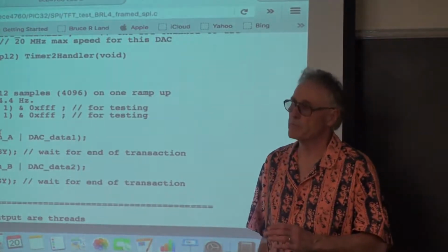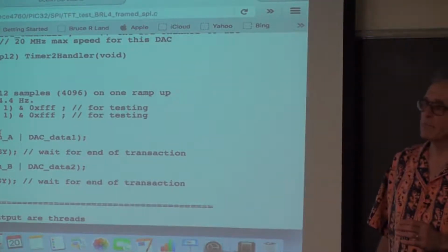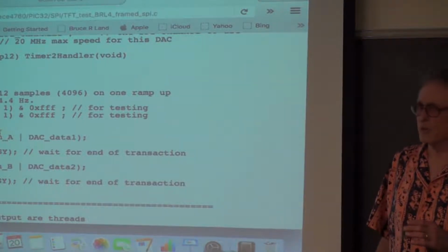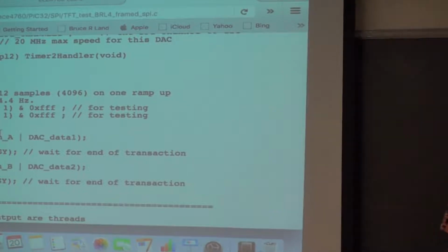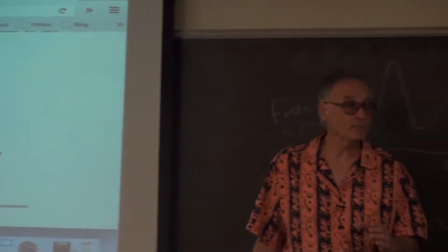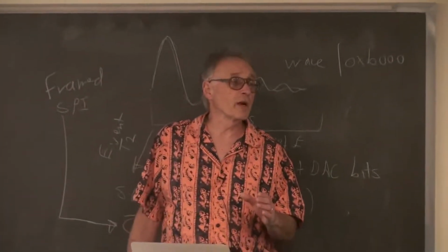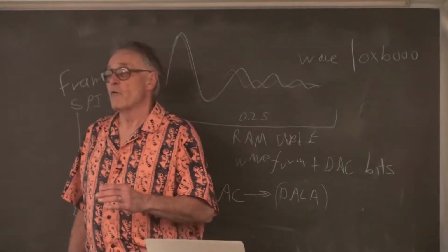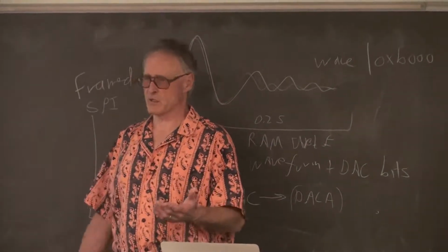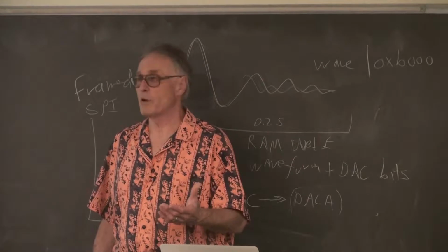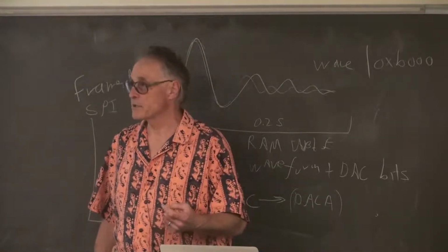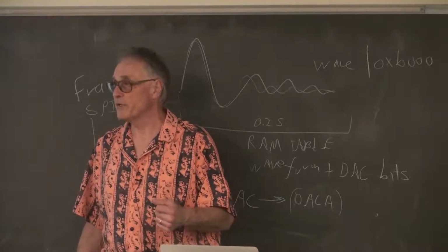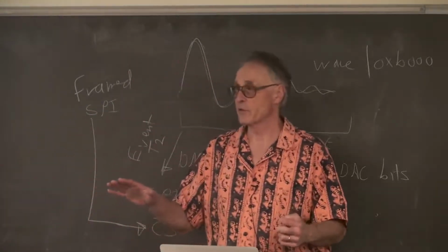Yes, that's correct. So how low a speed is that? Well, if the SPI is running at 20 megahertz, that corresponds to a 16-bit transfer in 3/4 of a microsecond. So if you're running at 44 kilohertz, that's 21 microseconds, right? So that's plenty of time for audio synthesis. The SPI channel is plenty fast enough.